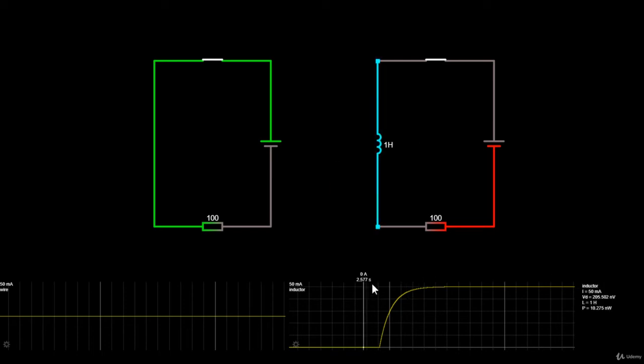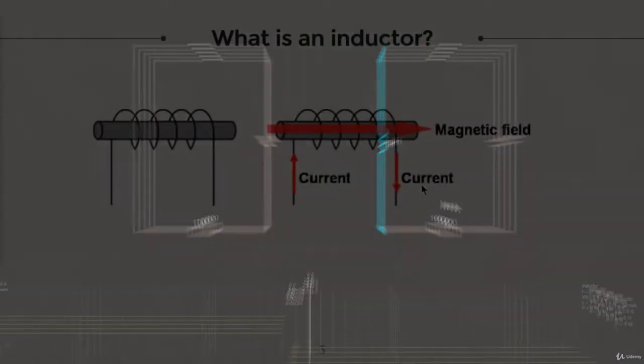We will have a dedicated chapter where you will find out that the resistance of an inductor is not called resistance, because only resistors have resistances. And this type of resistance is called impedance, which also tries to oppose the current flow. But it's a bit more complicated, not very much, but you will see that impedance is actually influenced very much by the frequency of the signal passing through it. And not only inductors have impedances, but capacitors too. Anyway, with this information, let's go back to the PowerPoint.